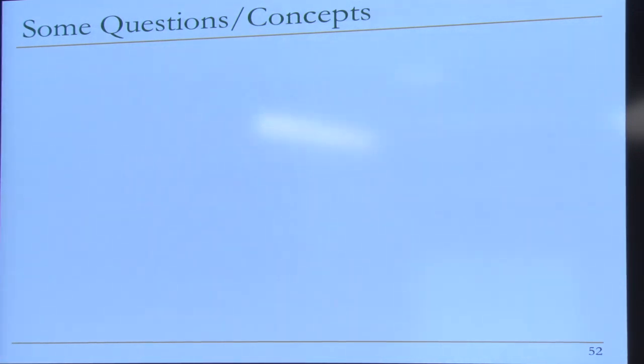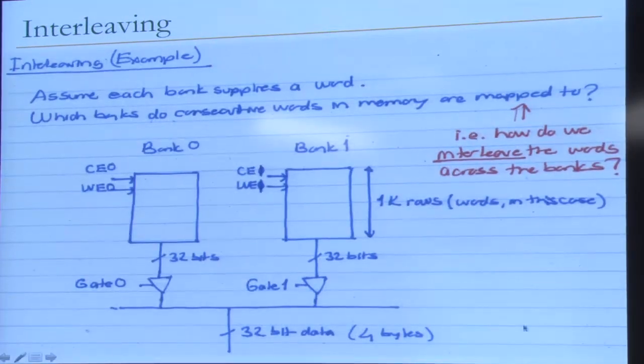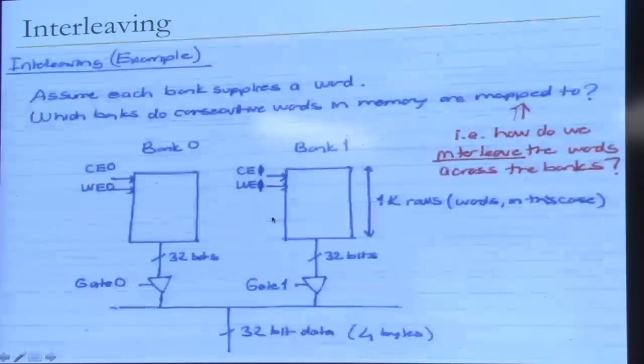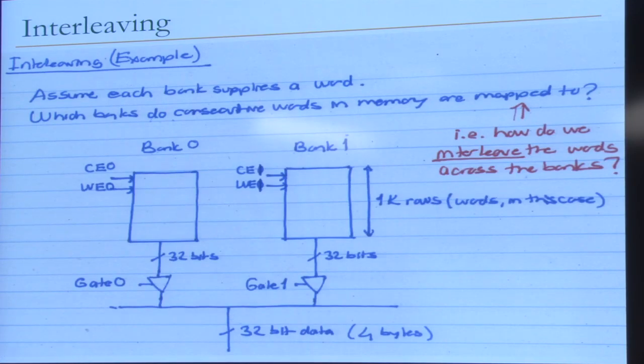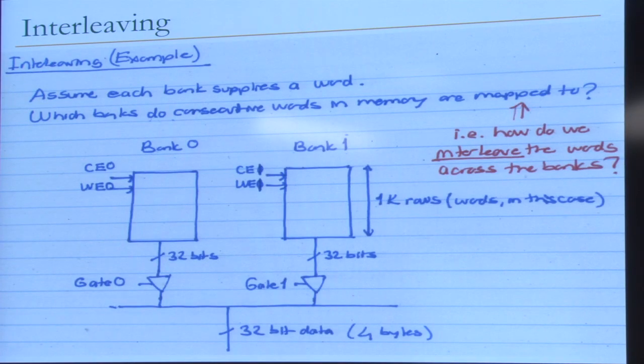DRAM banks look much more like this one. Whereas if you look at an L1 cache, they're relatively independent banks. They do not share the data bus. They can supply data independently because you have multiple load ports, right? You want to get the data to both of the loads at the same time. You don't want to pipeline them. Otherwise, you're not able to issue 2 loads per cycle.